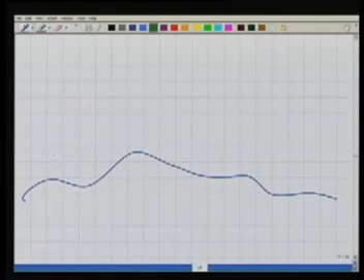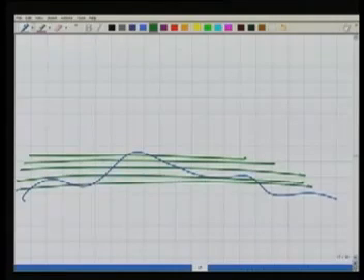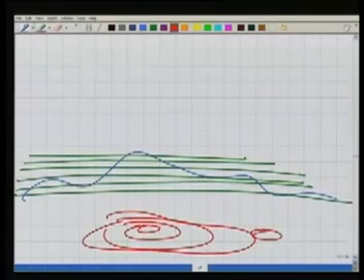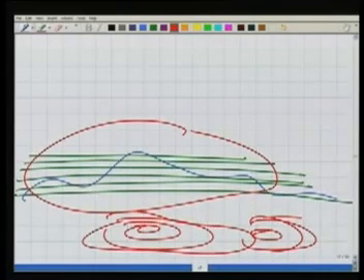So our aim is to capture the proper topography. So what we would like to do, we would like to keep our contour interval very small. So we have several contours there, so that our area, the topography is captured very well. So it depends upon the undulations. If the undulations are very large, we can go for large contour interval. If the undulations are very, very small, but we want to capture them, our contour interval will have to be smaller. Now third, it also depends upon the nature of work.